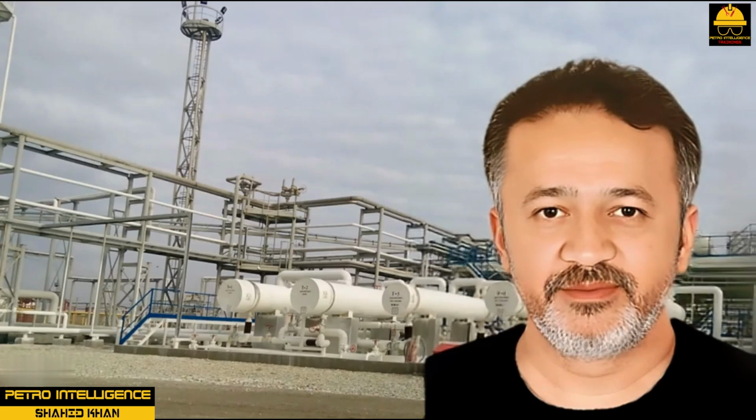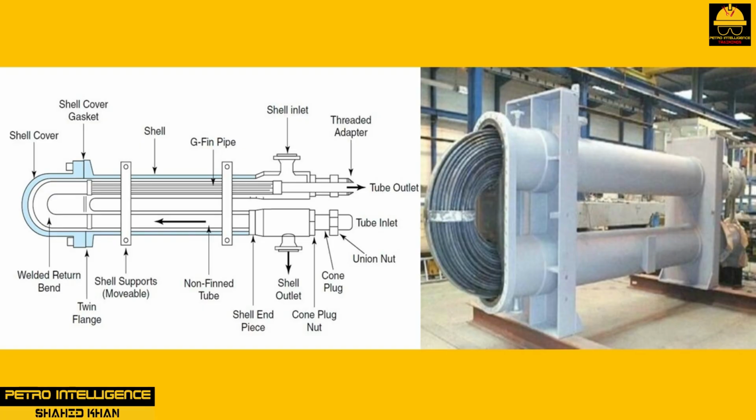Hairpin heat exchangers. The chemical processing industry commonly uses hairpin heat exchangers as shown in the picture. Hairpin exchangers use two basic modes, double pipe and multi-pipe design. Hairpins are typically rated at 500 psig shell side and 5000 psig tube side. The exchanger takes its name from its unusual hairpin shape. The double pipe design consists of a pipe within a pipe. Fins can be added to the internal tube's external wall to increase heat transfer. The multi-pipe hairpin resembles a typical shell and tube heat exchanger, stretched and bent into a hairpin.